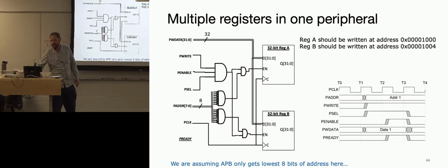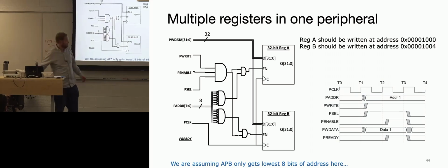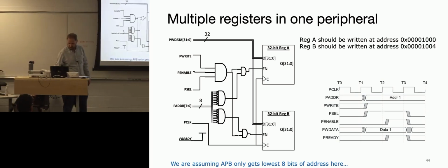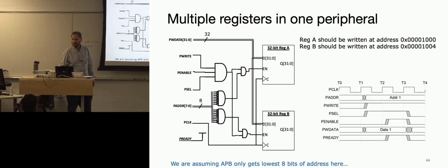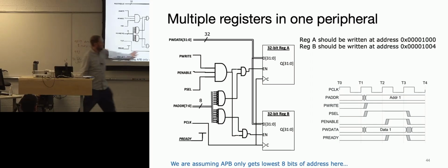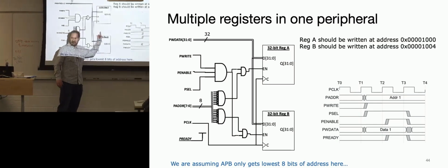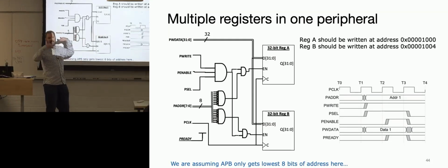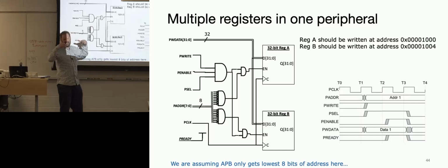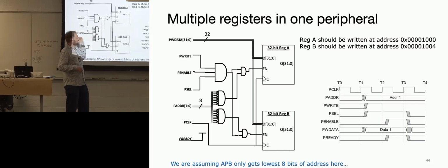Okay. Yes? Ready is connected to the power source. What is the power source? So these are combinational logics. Inside the D flip-flop, there's a line to power. So this is on the chip. I think the STMs actually run at 3.3 volts. So they have a power line throughout the entire chip, and this is available to be tapped into. And power VDD is just the same as logical 1.